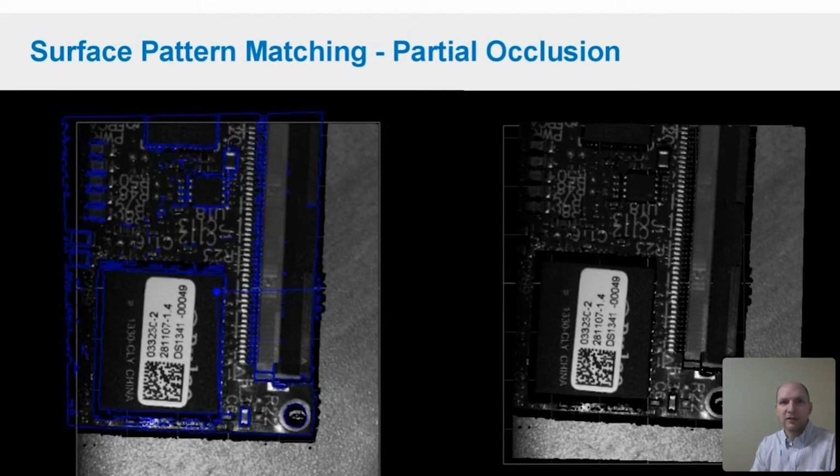And it doesn't take a lot to become familiar with it. You really just have to perform a scan, create a model based on your scan, and then you'll see it draw the outline of the part that it's detected the edges on. And then you can change your region to, for example, go from just seeing a small part of your surface to see the whole part, and then perform matching on that. It's quite easy to get up and going with that.